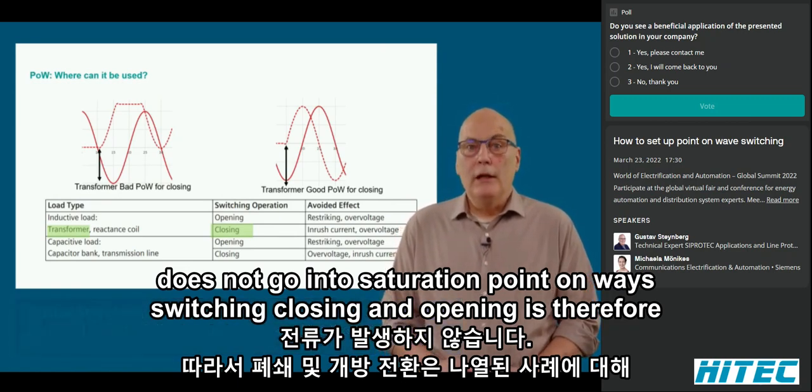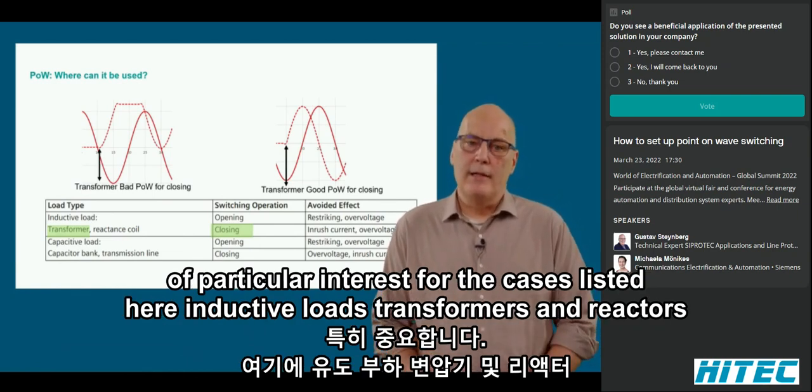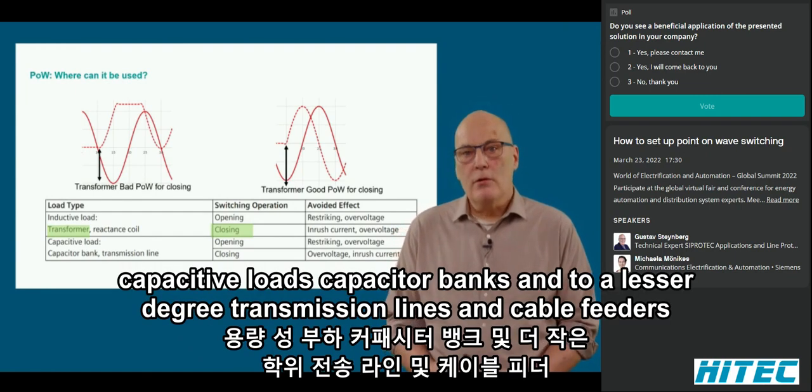Point-on-wave switching, closing and opening is therefore of particular interest for the cases listed here: inductive loads, transformers and reactors, capacitive loads, capacitor banks, and to a lesser degree, transmission lines and cable feeders.